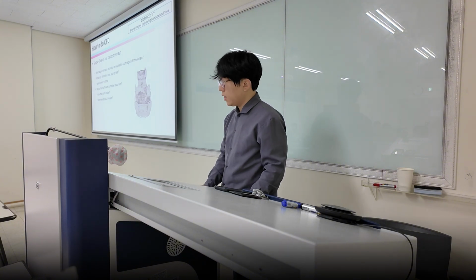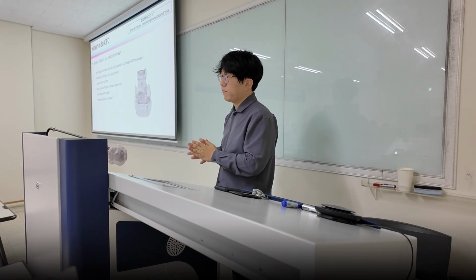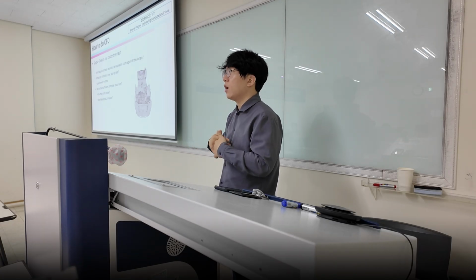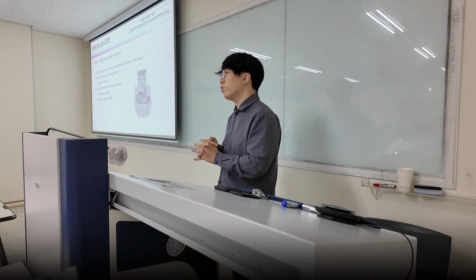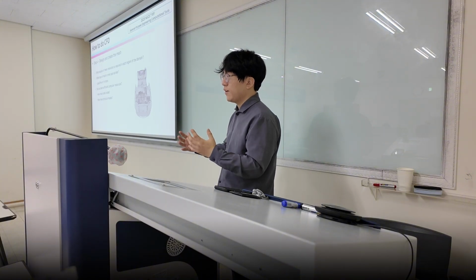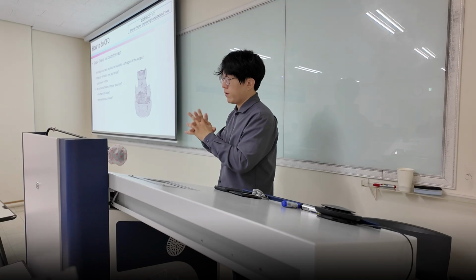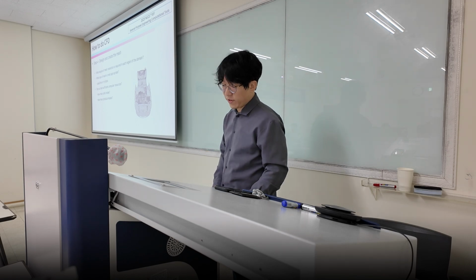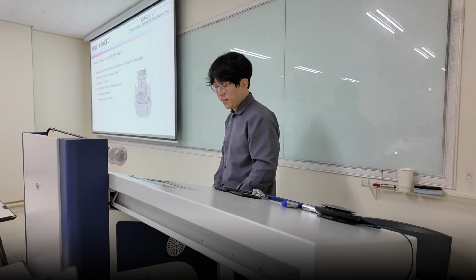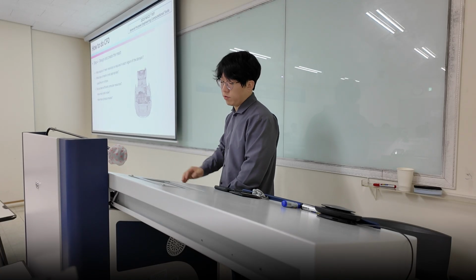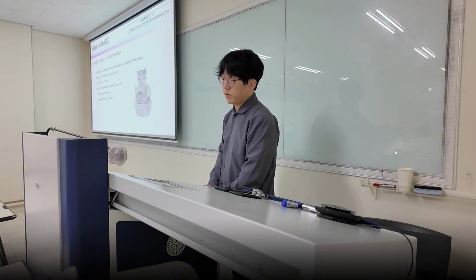It's really important because people would usually assume the more cores you have, the better performance you would have. But what really happens, from my experience, is that after 12 cores to 24 threads, the time it takes for communication takes longer than the saving of time. So it's rather unnecessary to have more than, let's say, 24 threads, for me. But it depends on the parallelism, and also these days they're applying a lot of GPU parallelism as well, so it saves a lot of your time.